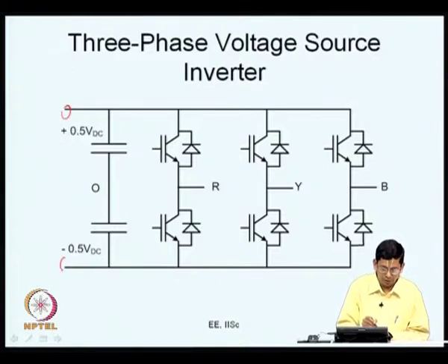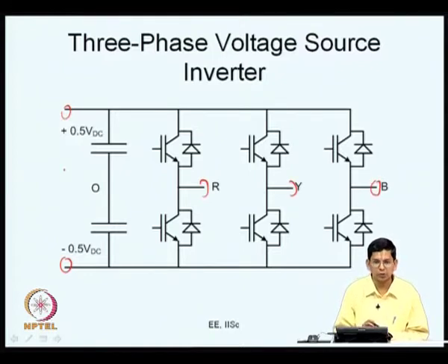And you have the AC terminals here. The DC supply could be connected between these two terminals, and the 3-phase loads can be connected to the terminals R, Y and B. So, there can be an inversion now. This DC can be a DC supply or a battery bank. In a UPS, it is typically a battery bank, and it can be a DC power supply, or another converter which gives DC. So, you can feed an AC load here.